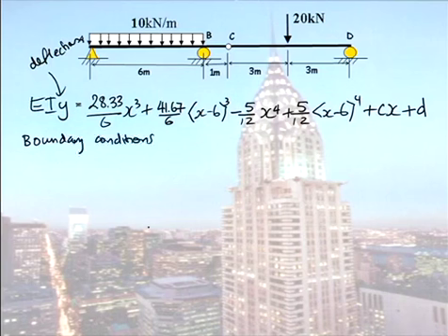And those boundary conditions, the first one would be when x is 0, y is 0. So in my equation I would plug in 0 is equal to 0 plus. Now this is where people go wrong. If you look at this bracketed term here, it's x minus 0. And people say, oh, so do you apply the singularity rule there?